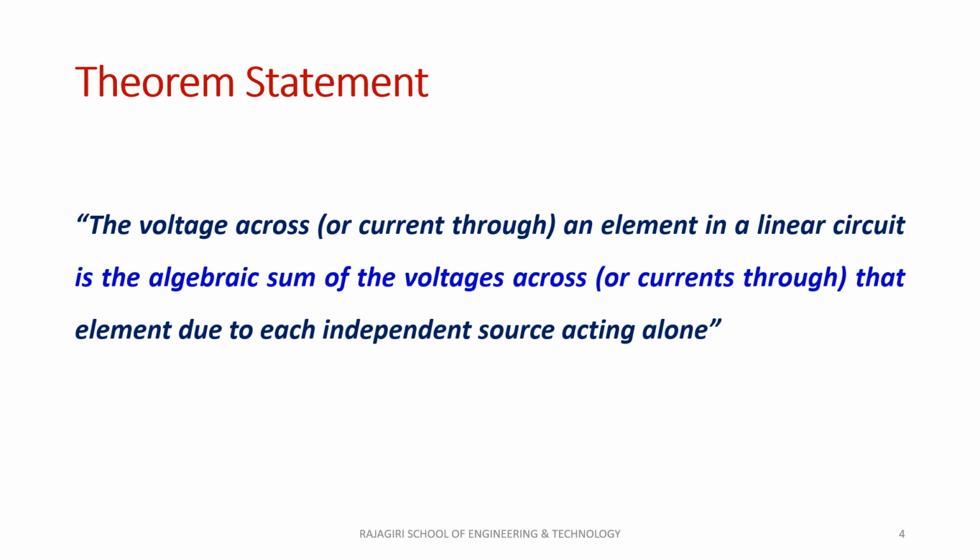Linearity implies that all the elements in the circuit must be linear. That is, the voltage-current relationship in these elements must be linear. By homogeneity, we mean that if the input is scaled by a certain factor, the output must also scale by the same factor.